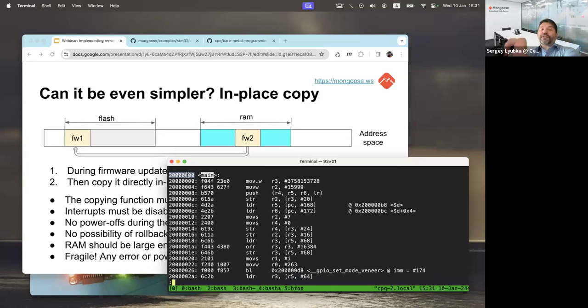So it's not flash anymore. This trick that I've shown you allows you to put any function or any variable there. Variables go by default to data, so there is no reason to put them into the data section this way.